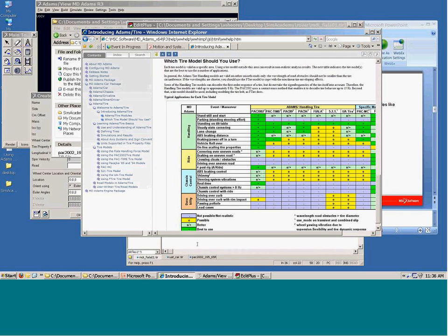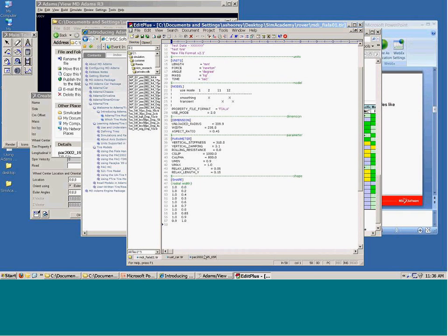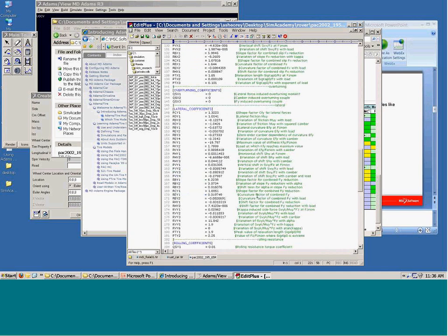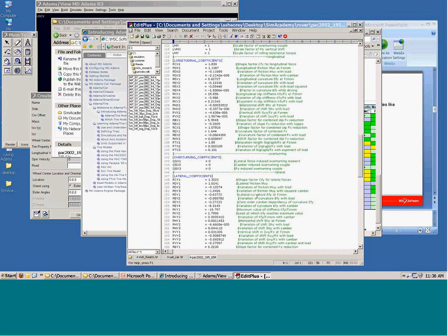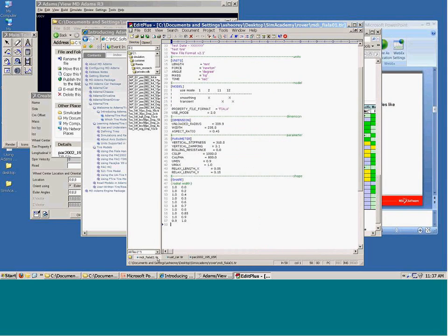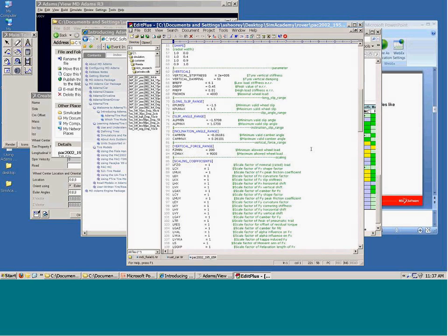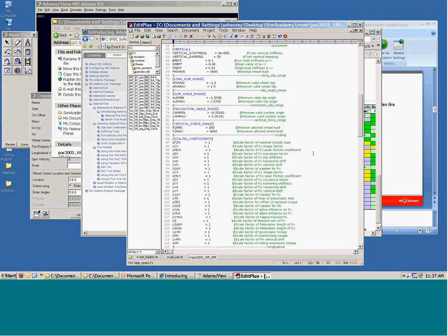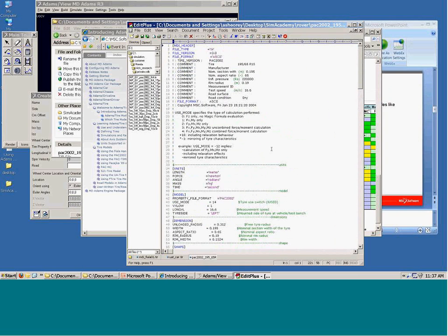To generate these kinds of tire property files, you have to actually go and physically test a tire, and then you fit the test data and compute these coefficients. So this is more like an empirical approach, whereas the other is more like a physical math expression: stiffness, damping, slip. Each tire would have different coefficients depending on the test format and the situation it is tested on.